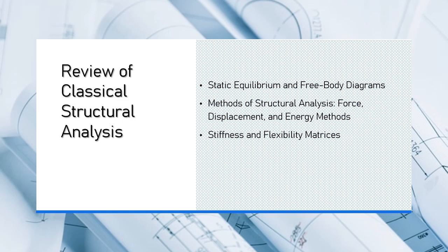Key features of force methods. Useful for analyzing structures like beams, frames, and trusses where the number of unknown forces exceeds the static equilibrium equations. The method requires knowledge of how the structure deforms under load, i.e., how forces are distributed. Example: in a continuous beam with supports that are not simply supported, force methods can help calculate the internal forces by introducing redundant supports and applying compatibility conditions.